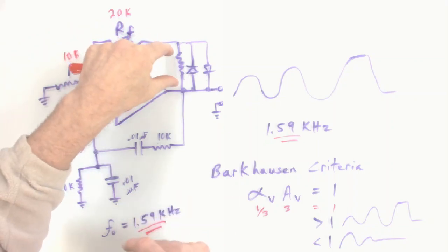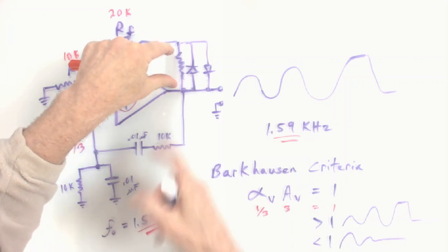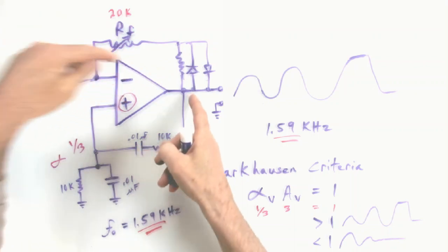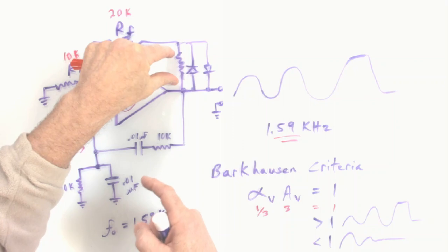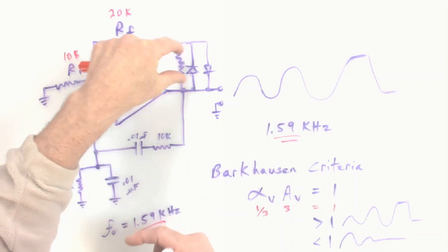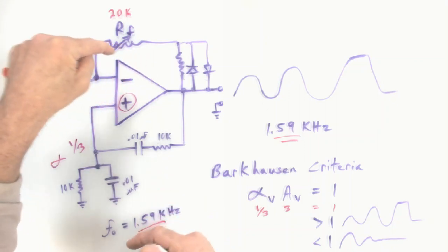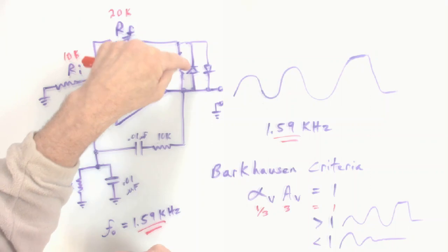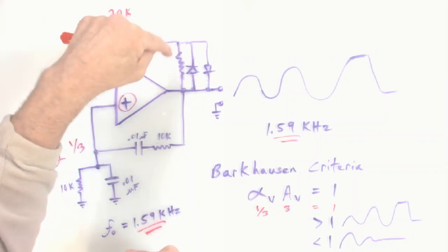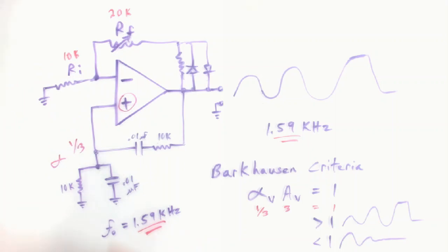It can only go so far, and the limit to so far would be the voltage at the output that causes, yes, it's across all of these resistors, but it'll cause an IR drop here that, when it gets close to 0.5, 0.6, 0.7, that's the end of it, because the IR drop will be turning on diodes that essentially short out the resistor and lower the gain. So it's another way you could regulate the gain.